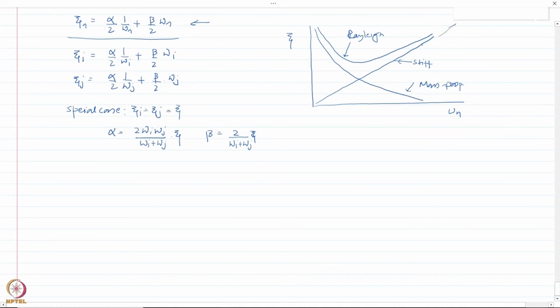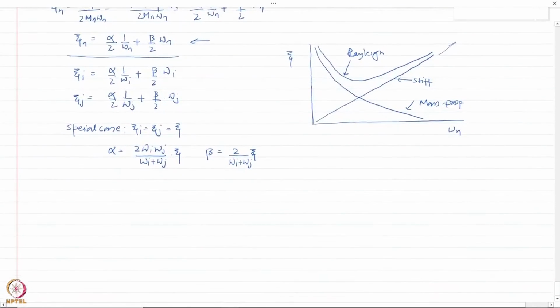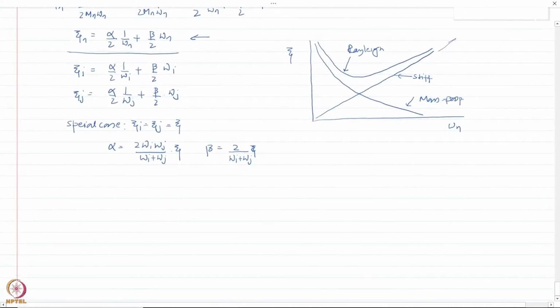Similarly, for mass proportional damping, if we specify it based on some modes which are not the primary mode, then greater than intended damping would be assigned for smaller modes. However, through Rayleigh damping, we can choose the modes to which the damping needs to be assigned, and for all the frequencies that lie between them the damping would be bounded.